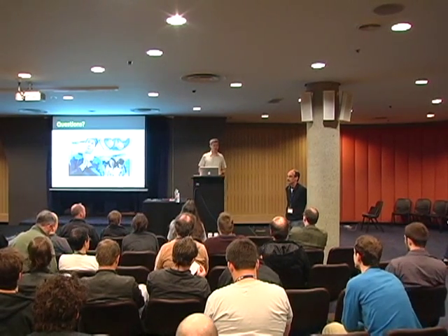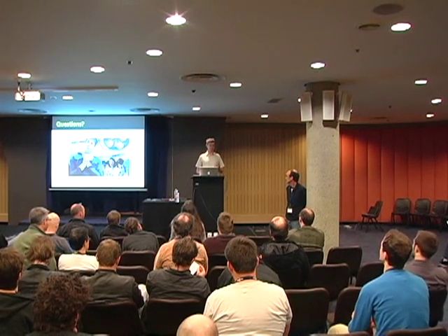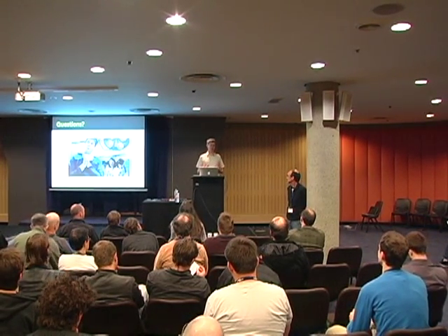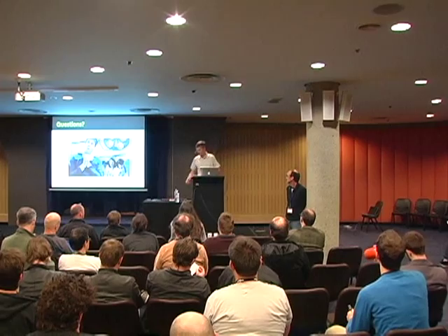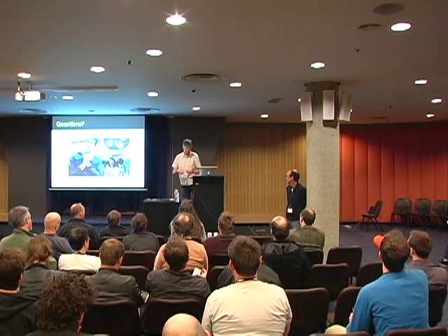I think servo motors are really good because they're not complex like stepper motors, but you can use them to drive lots of things. And they're so cheap. You can walk into a Jaycar and buy a servo motor. Something like this has 3 leads, $10, $12, including the gear bits. So you could wire that up to a propeller, you could wire it up to a gauge, you could wire it up to a little man that waves at you whenever you get a tweet, whatever. I think those combined with LEDs are probably the best outputs for starting. In terms of inputs, having some switches is always good just for debugging and testing, if nothing else.